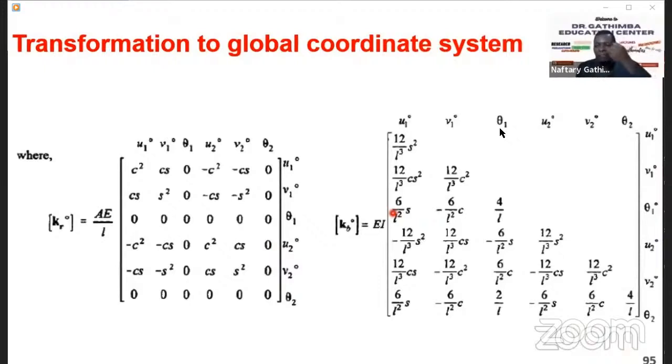If we have very rigid members, where axial rigidity and stiffness are high, and we're not considering deformation, then it means this component may disappear. But let's see with an example what this means. And we also see a case whereby we can use the combination, where we use the stiffness matrix when we have incorporated all the components for the truss and for the beam directly. So those are the two different approaches that you can use.